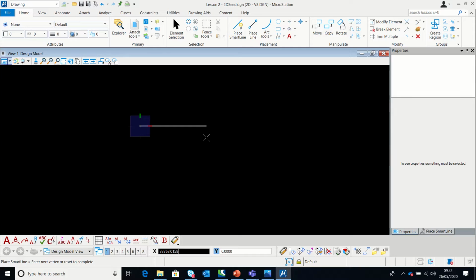Then you can type the length you want. So I'll type 100 here. You see now that's 100. Then you click once, then you move your mouse again. Then you find another area which you want to lock. Now I want to go up this time, and I will press 50. Then you press enter on your keyboard. Then that puts a 50 mark. You can see there. Then you click again using your left button of your mouse.